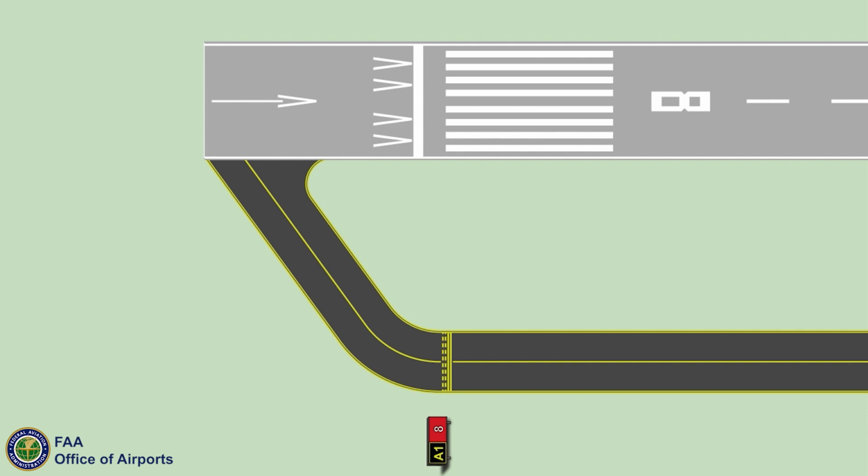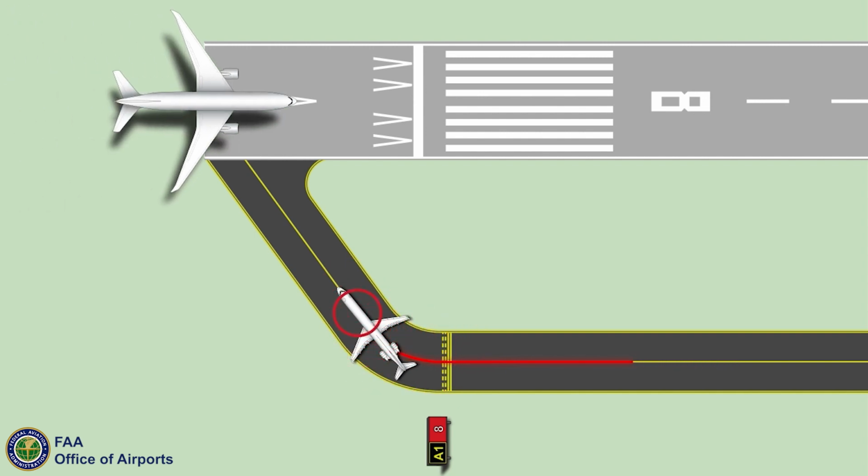Runway hold lines not located at the typical location on the 90-degree entrance taxiway introduce higher risks for runway incursions. Sometimes, hold line locations are on the parallel taxiway. This may be when the separation between the runway and taxiway is not sufficient. In this scenario, the pilot encounters the hold line in an unexpected location and may inadvertently proceed past the hold line, resulting in a runway incursion.